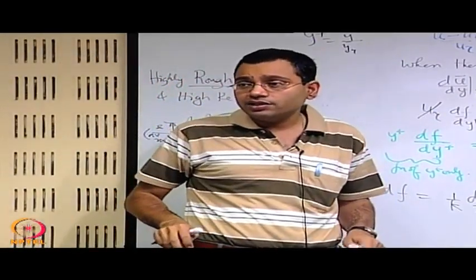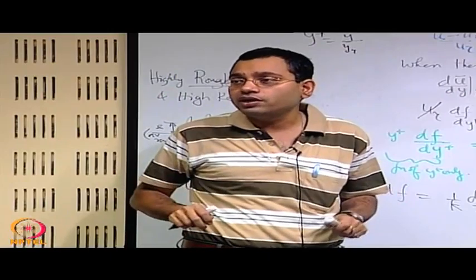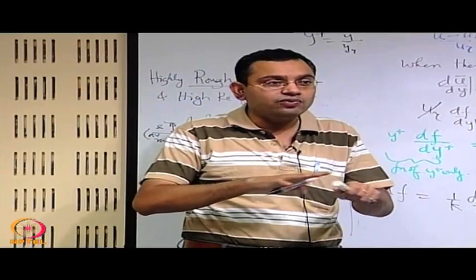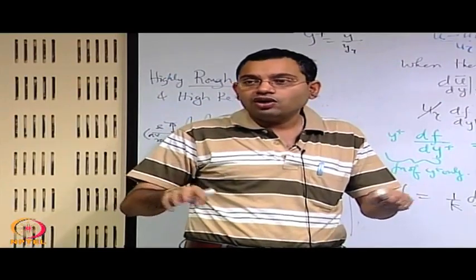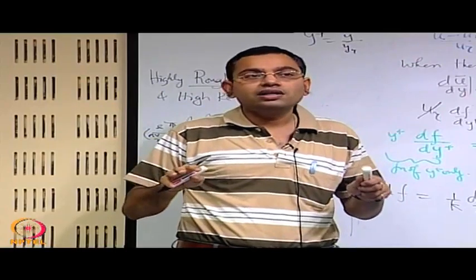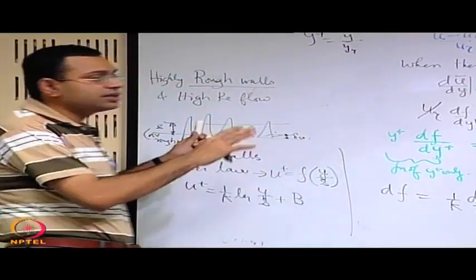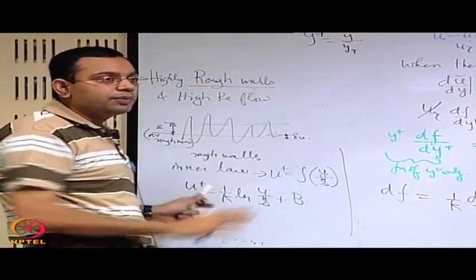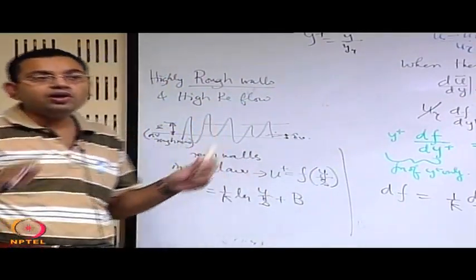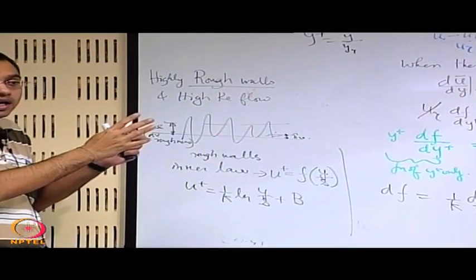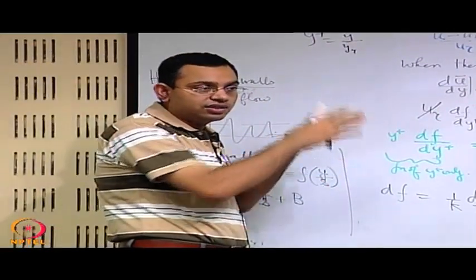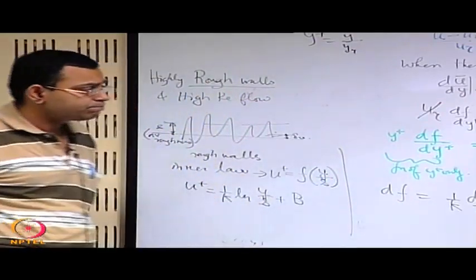Why is that important? That is important because many of the flows in engineering are wall bounded flows, maybe flow over a plate or a surface, or maybe flow in a channel or a pipe. So the effect of the wall in dictating the turbulence is what is important, and somehow we could develop a qualitative picture or a very simple quantitative picture from the broad understanding, and you see that Prandtl's mixing length helped us a lot in understanding the actual functional dependencies on the various parameters.